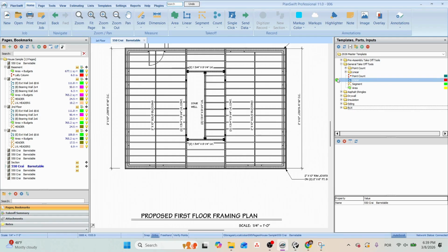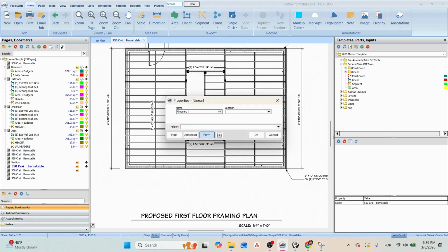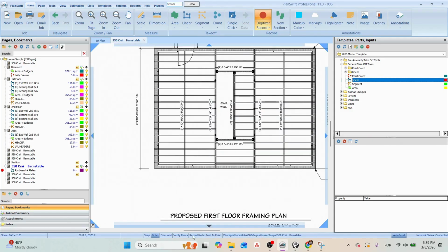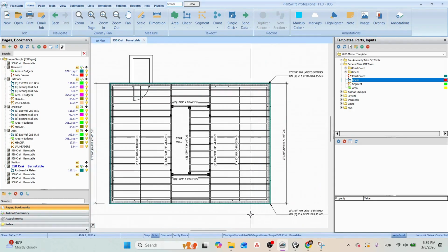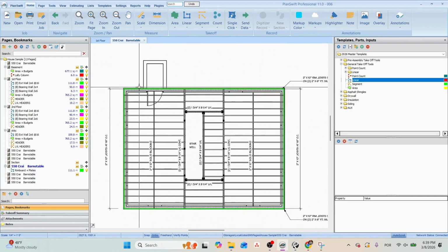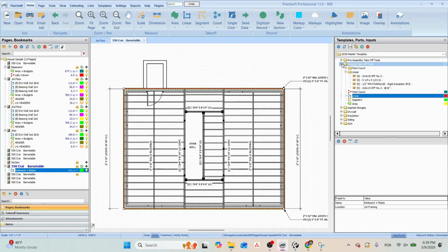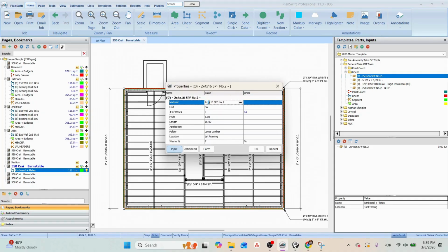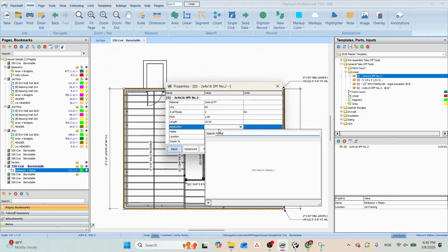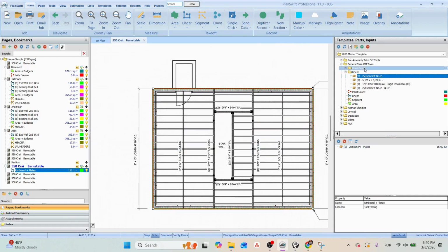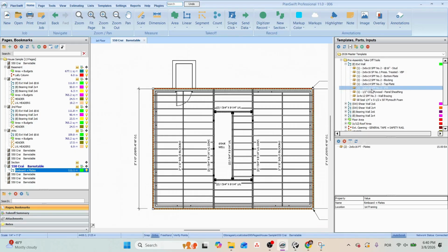Let's go into general. Mortise plates. For framing. It's a rectangle. Save some time already. Cool. So it's two plates, 2 plates, pressure treated green, 2-by-6 plates. Sill, we can take them from the walls.